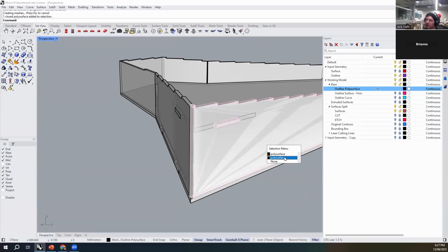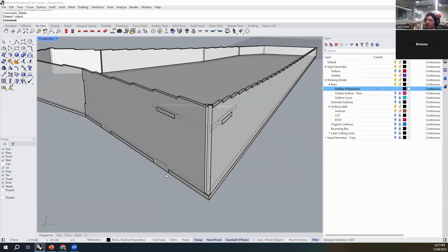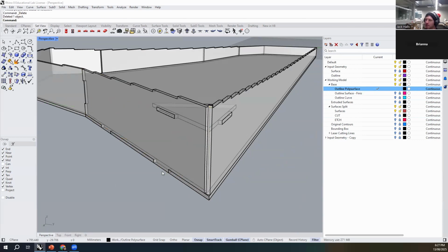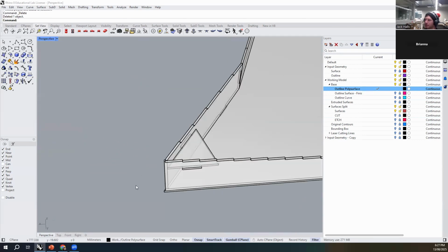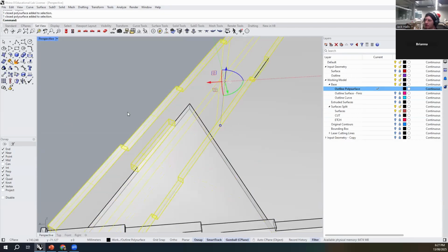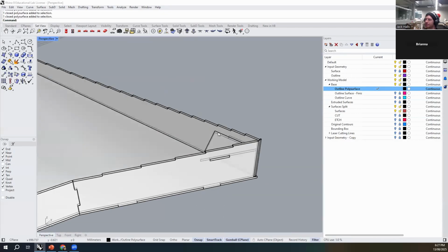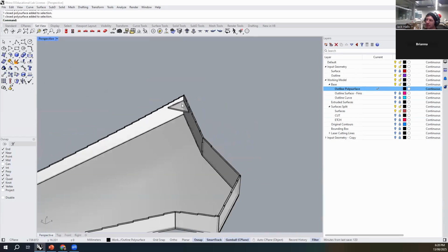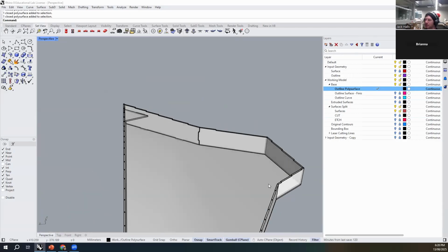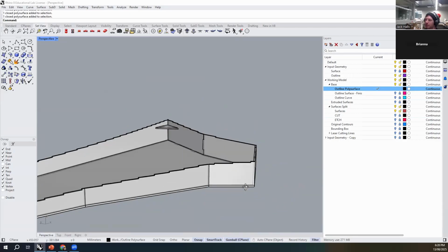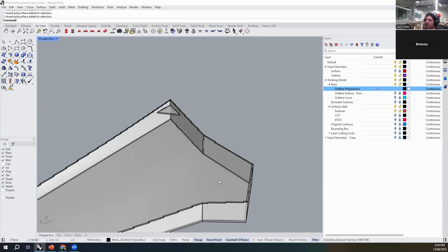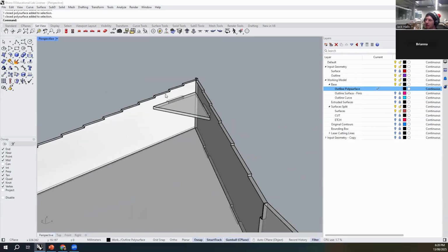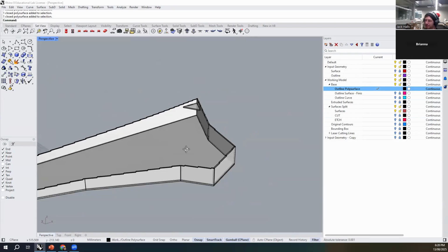You can see again with that Boolean difference, we've got 2 inputs. I just want to get rid of the input geometry. It might just be that when I did the command, I didn't have my settings quite right, so just check that for yourself. And we've got, yeah, those 2 geometries. So including wedges or supported wedges like that into each corner, they can be large, they can span large sections or whatever you feel is required. It's going to really help you bring the model together and give it some proper structure.